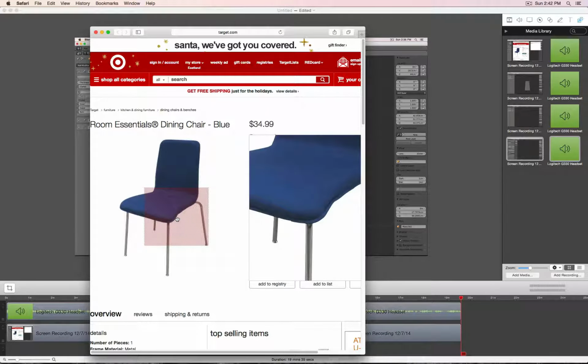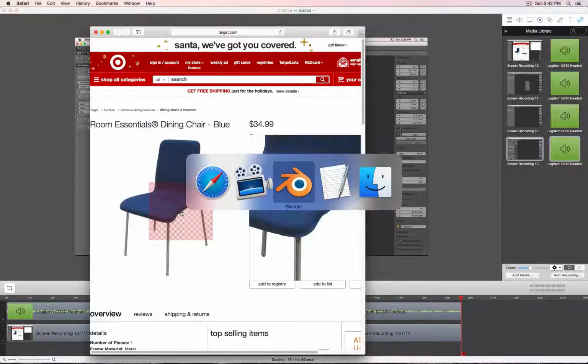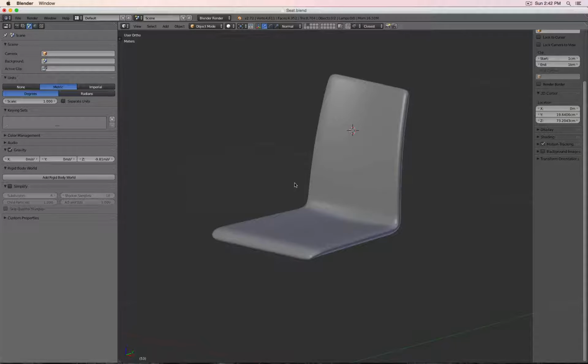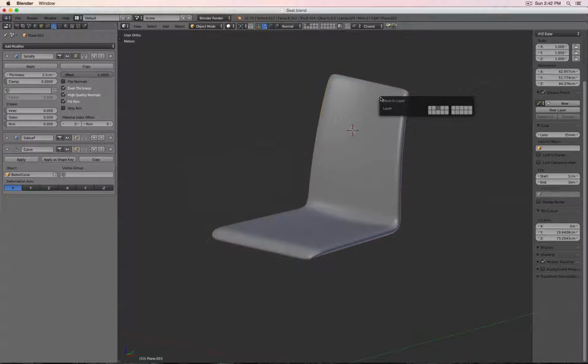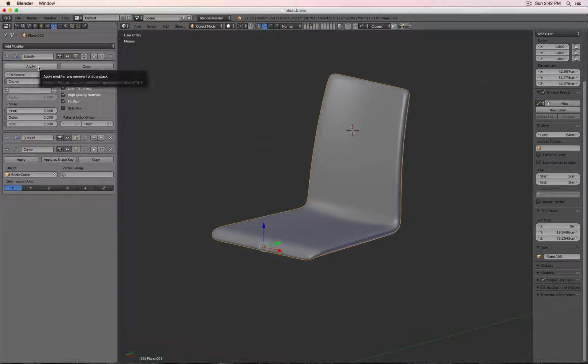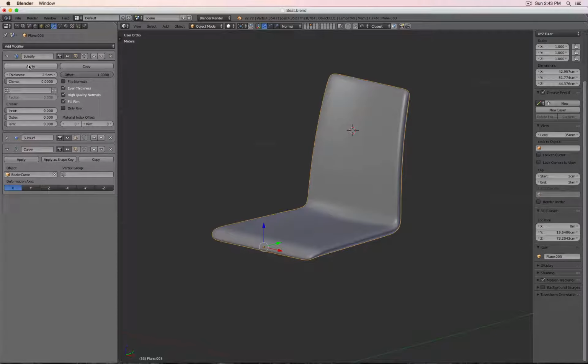So the seat has a small seam, roughly 5 millimeters, kind of like a circular cross section. That one's pretty easy to build. So I select my object, Shift T, Escape, M and 3, put it onto layer 3, so I keep my original model intact. And then here I apply my solidify modifier, because currently I just have a flat shell.